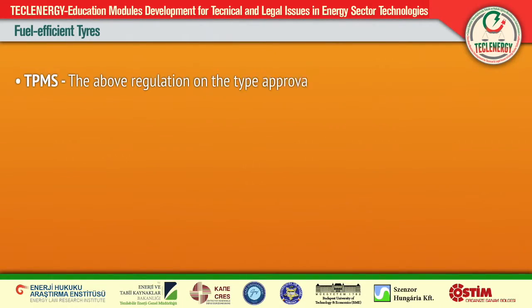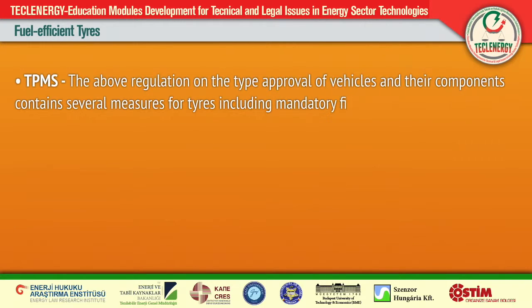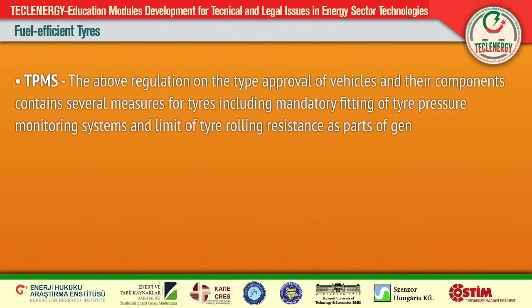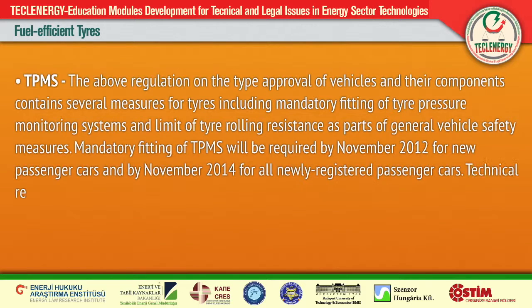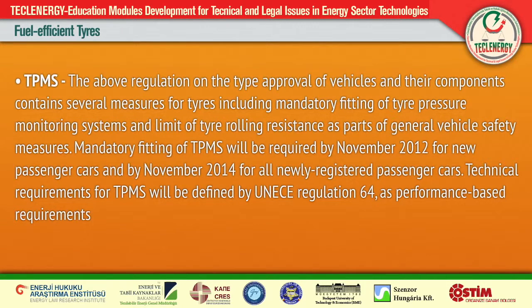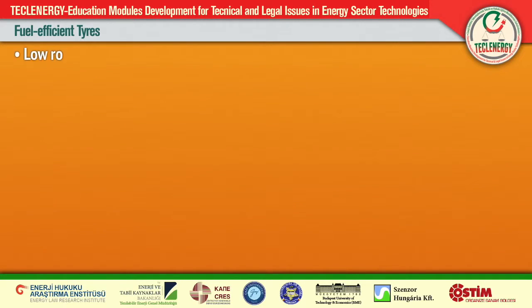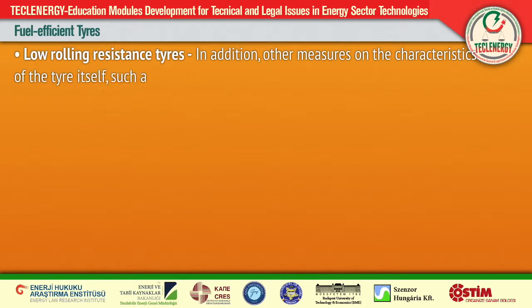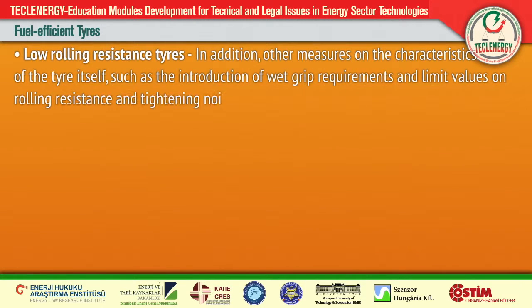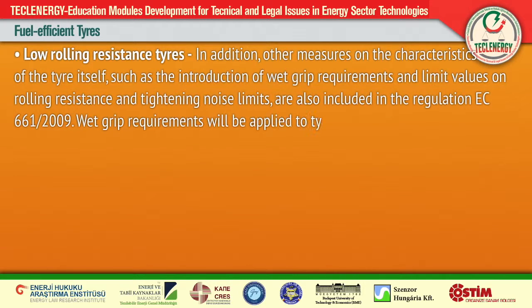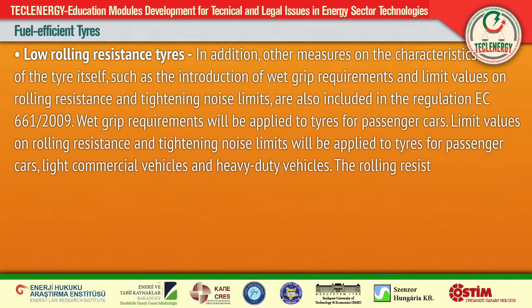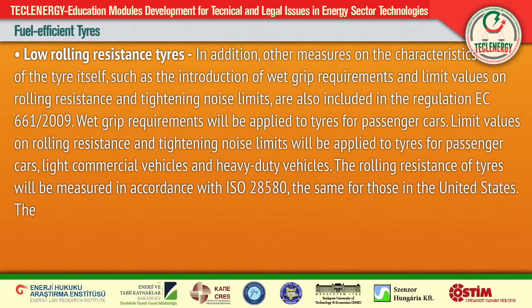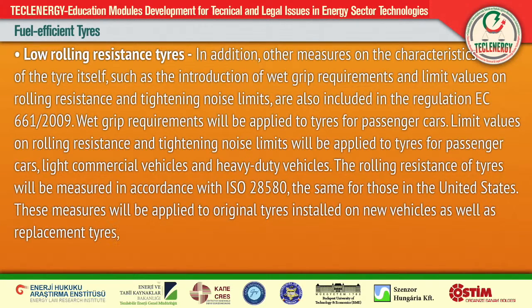Roughly 20% of a motor vehicle's fuel consumption is used to overcome rolling resistance of the tires, IEA 2005. The amount of rolling resistance is a function of the level of inflation of the tires and the technical rolling resistance of the tire material. Additional fuel is required when tires are underinflated. In most real-world driving conditions, tires are underinflated compared to their optimum performance level. Tire pressure monitoring systems are a valuable tool for both car safety and fuel economy purposes. Information is sent to drivers when their tires need inflation, which encourages better vehicle fuel efficiency.